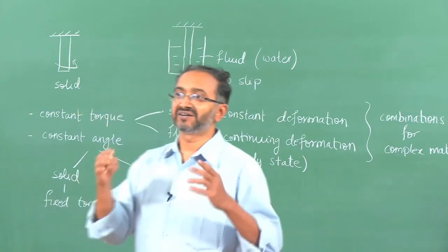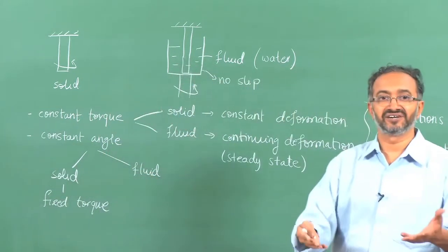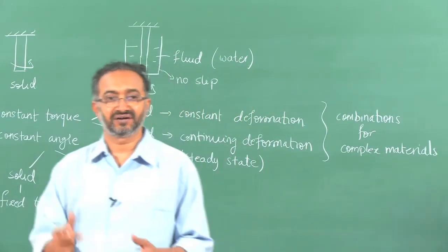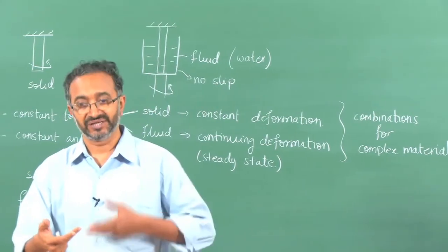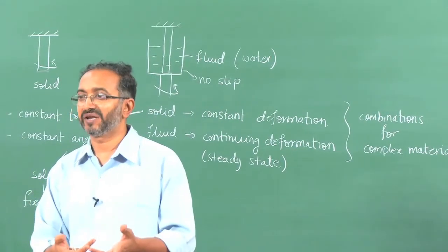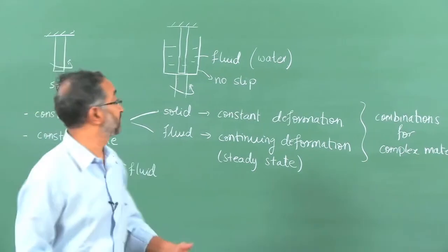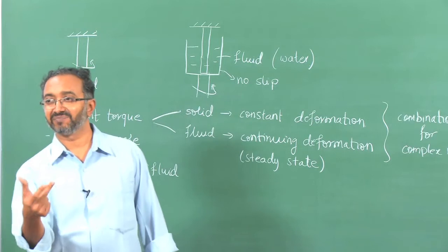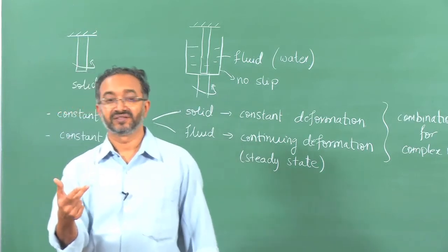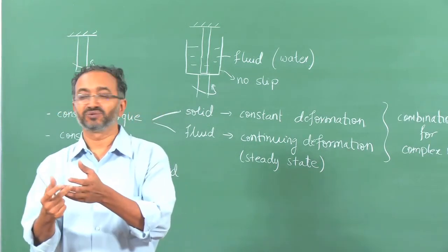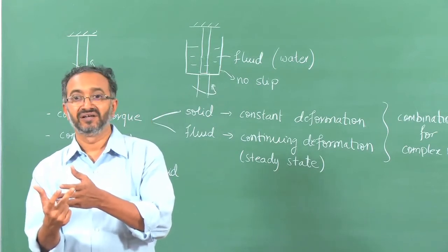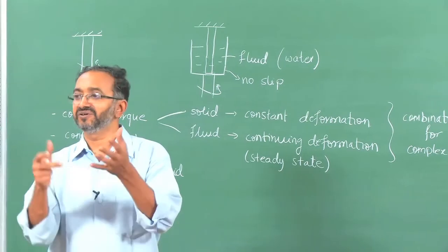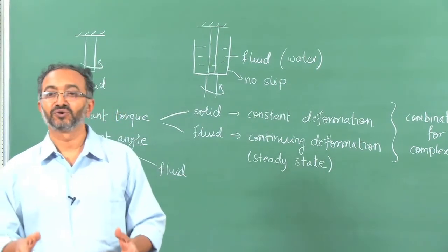In school we learn that a fluid cannot withstand shear, that is this property, that once we allow some deformation, during that period torque will be applied. In fact, why is torque required? Because we have a velocity gradient in the fluid while we are applying the rotation, therefore torque is required. But as soon as I finish the deformation, there is no rate of deformation in the fluid, and therefore no torque is required.